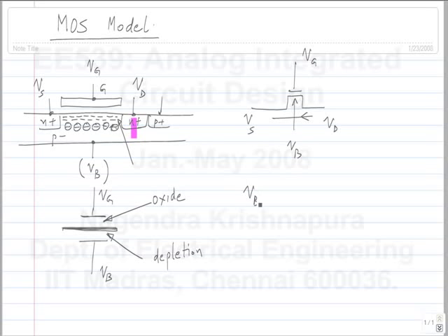Okay. So let's say VB should be maintained less than the minimum of source and drain voltage, and possibly you can go about half a volt above it, but definitely not more. Then you will end up with a significant current through the forward bias diode. Okay. But there have been circuits made recently successfully in which you do forward bias by about 0.3 volts, thereby lowering the threshold voltage. Okay. A lower threshold voltage does have advantages in an analog circuit.